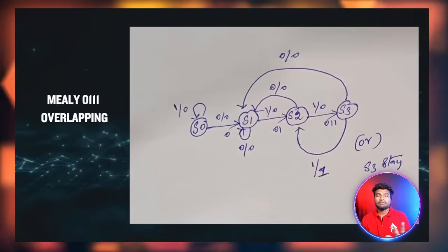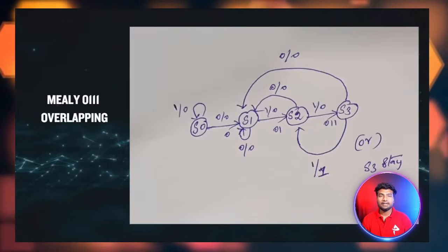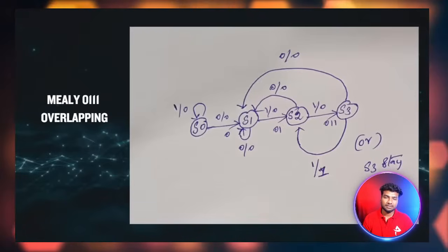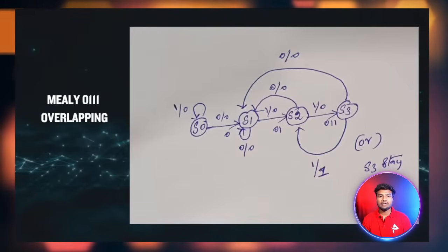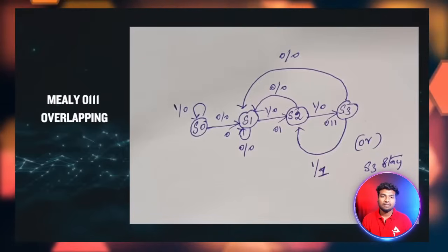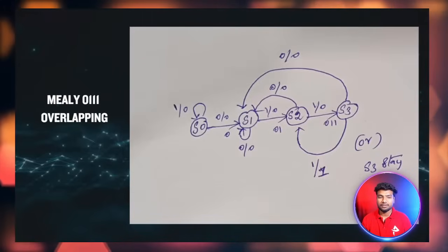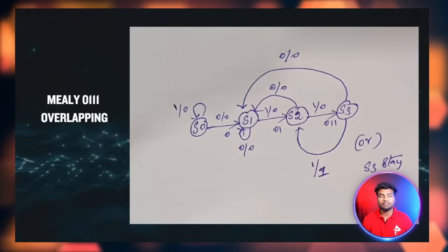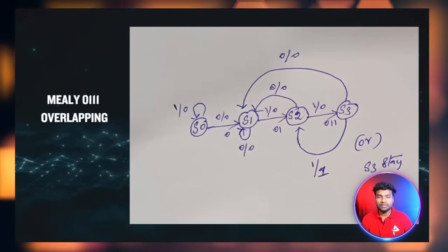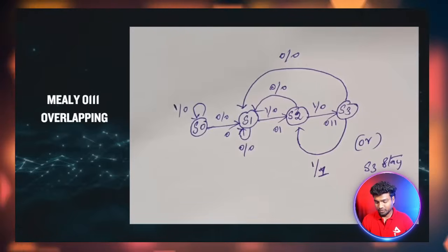The main thing is that the FSM needs extra states while dealing with states. For a 4-bit sequence you would expect 4 states, but in the Mealy machine you need 5 states.